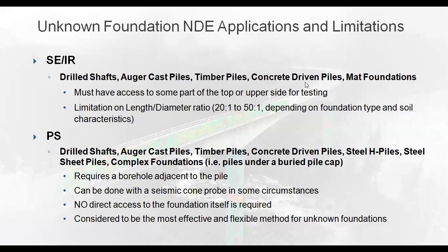The sonic echo impulse response method is primarily used for drilled shafts, auger cast piles, timber piles, concrete driven piles, and can also be used on mat foundations. It has a couple of basic limitations. For the SEIR method, you have to have access to some part of the foundation itself, either the top or the upper side. Sometimes you can do this method through a pile cap. Sometimes you can do it through an actual slab. There are some limitations on those based on the geometry, the diameter of the pile, how thick the slab is, etc.